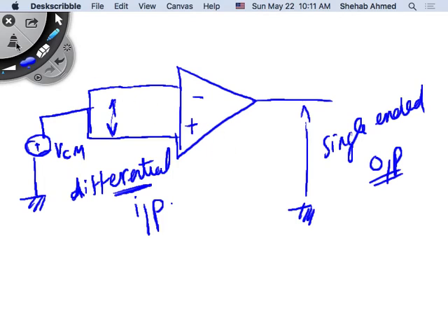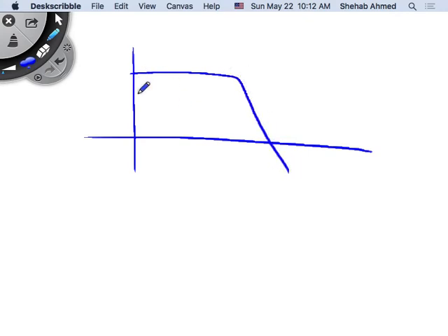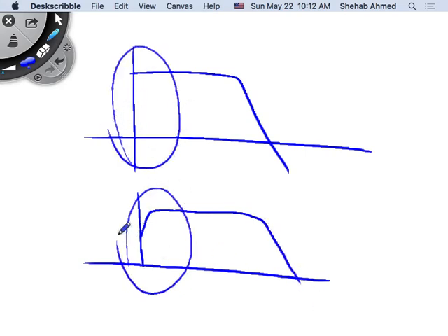Okay, what else? We said we also later... I mean, so we talked about the DC coupled amplifiers, right? We said DC coupled amplifiers are ones that do not attenuate the signal at DC. So this is a DC coupled amplifier versus this is a capacitor coupled amplifier. This is an indication of that. Op-amps, we said, are DC coupled amplifiers. Is this good or bad? Again, later in the chapter we will see that this causes some limitations.